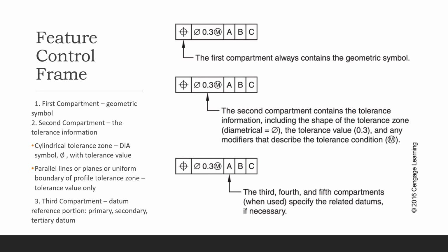Just by looking at it, I want you to go back to the table and review the symbol, what it is talking about, and the datum here. If we box them, we call that the frame. So if I say feature control frame, I am talking about this thing, and it tells you information on how to do that measurement.